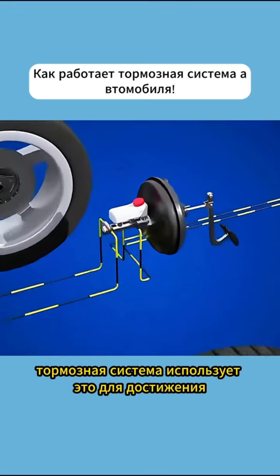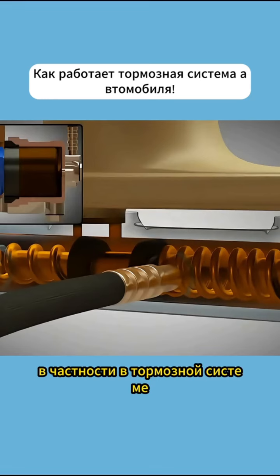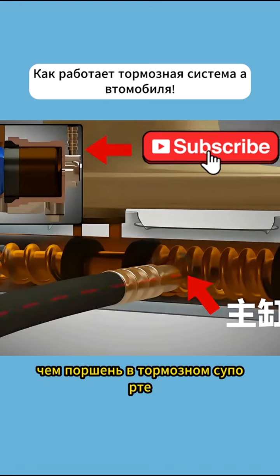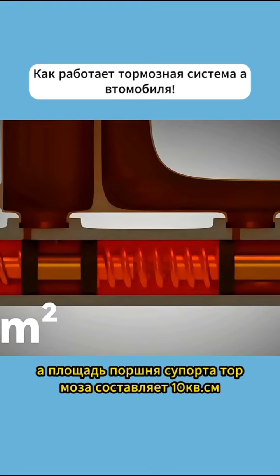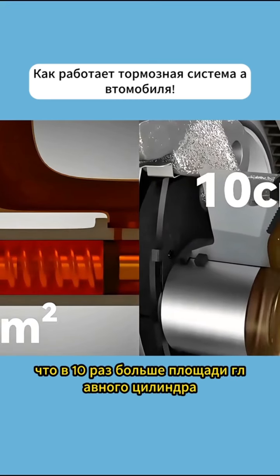Therefore, in a hydraulic system, the force and area of different pistons or areas are proportional. The braking system uses this to achieve force amplification. Specifically, in the braking system, the master cylinder and the brake caliper have pistons, and the area of the master cylinder's piston is usually much smaller than the piston in the brake caliper.